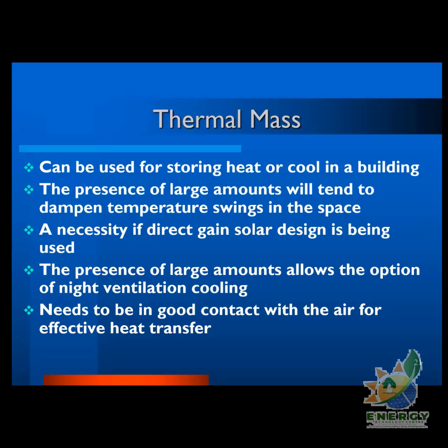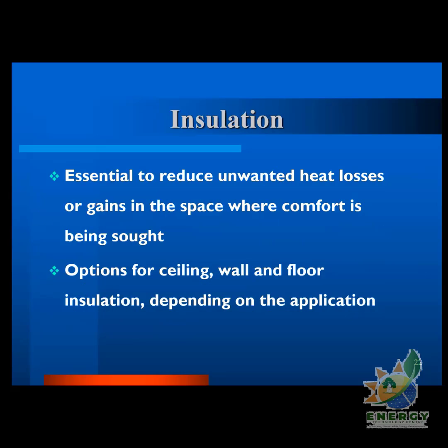This thermal mass needs to be in good contact with the air for effective heat transfer. So the best area for thermal mass would be the floor and then the walls, especially the floor area, where you try to introduce a lot of thermal mass so that you can absorb a lot of energy during the daytime, so you reduce the need for cooling, and then during the night it's possible for the heat to be lost.